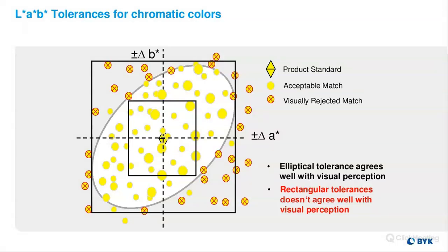That's good. Definitely you should have samples that are visually acceptable, visually okay, and visually out of tolerance, so that you can figure out what equation to use and what matches best what you need for your parts and your process too. Some people's processes may have a lot of variation, and if we make the tolerance tight, they're never going to make it. Then everyone just looks at the number and says it fails all the time, and they think the instrument measures incorrectly, when it has nothing to do with the instrument itself. It has to do with the color equation that I'm using.